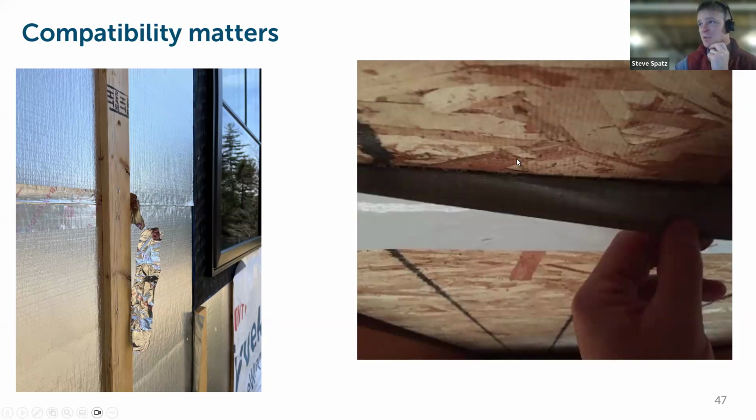There's another example as well too. These are SIPS panels, so structurally insulated foam panels. It's EPS behind that OSB there. And the builder in this example chose to make the effort of taping the seams of the SIPS panels to seal them up, make them airtight, quote unquote. But that's a staple right there. So the tape was actually stapled to the OSB because it wasn't sticking. So that's another example of someone just kind of blindly going through the day, wasting materials and time and outcome.